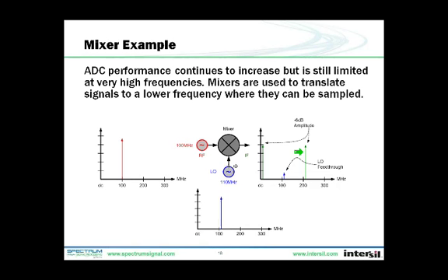So one must be filtered in front of the mixer from the RF signal. For example, an RF signal at 100 megahertz, as shown, mixes with 110 to create a 10 megahertz signal, but one at 120 megahertz would also mix with 110 to create another signal at 10 megahertz. So you have to make sure and filter that undesired RF off.